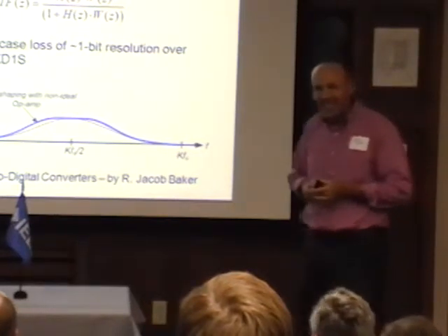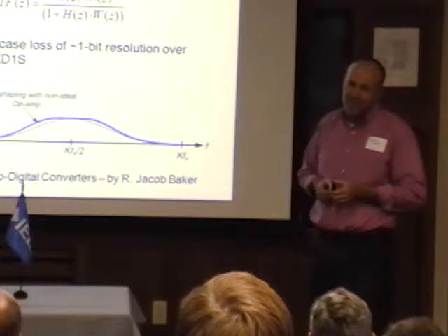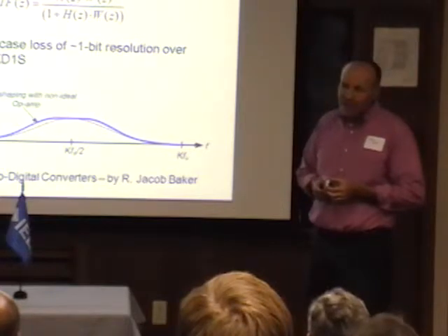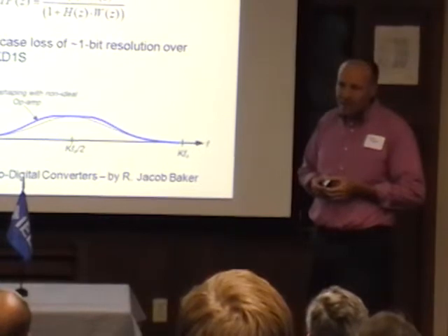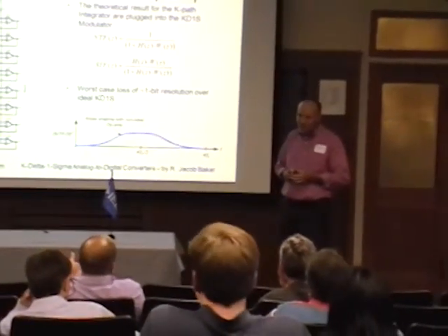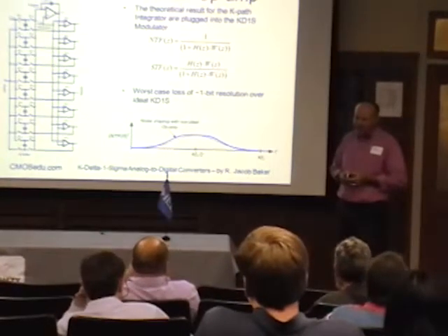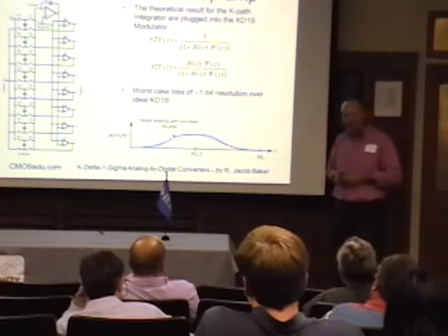Does that make any assumptions about the correlation of the signal to your clocking, being totally asynchronous? As you mentioned, in SerDes systems, if the data rate was somehow linked to your clock rate, and you had some non-uniform clocking, you fall into the same periodicity with your signal, and it shows up. I can think of all kinds of issues there, so I don't know. I have to take some thought.